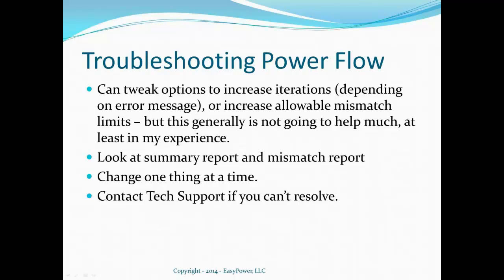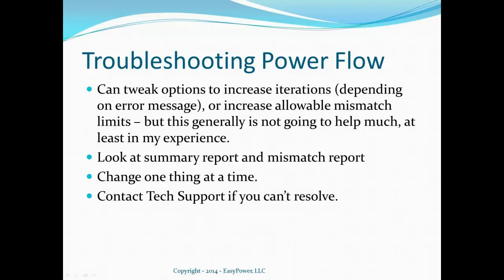Question: should the power flow model be created with the worst case power demand, or should a demand factor be applied? So you want an actual real power flow case. You want the actual real world power flow or whatever you're trying to simulate. So the demand factor is not used in power flow. That's only used for the NEC sizing type calcs. So changing the demand factor will not have any effect on power flow in EasyPower.